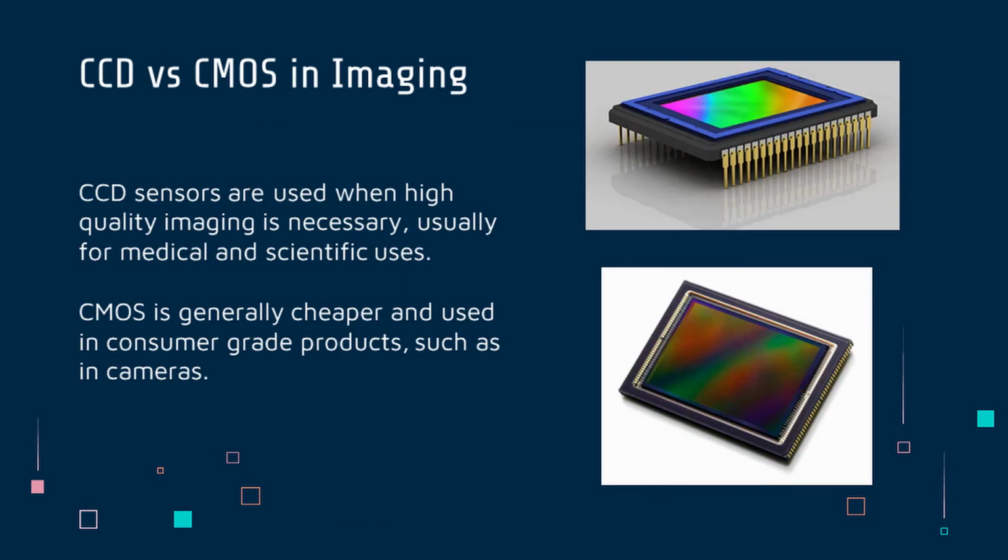CCDs and CMOS sensors have been competing for many years. CCDs have passive photosites that capture information and move it to an amplifier. In contrast, CMOS has amplifiers at each local photosite. This means that CMOS sensors can have more variation due to having more amplifiers, which results in having more noise. CCDs also generally have higher quality pictures and have better light sensitivity and less noise.